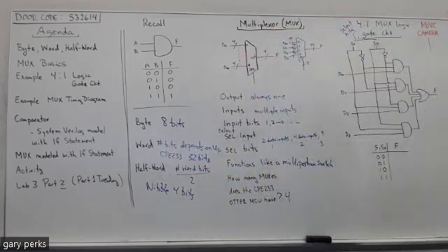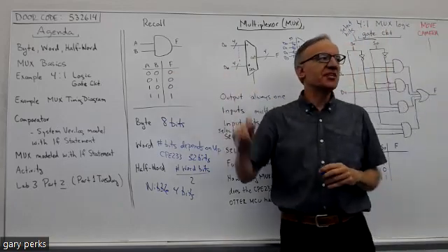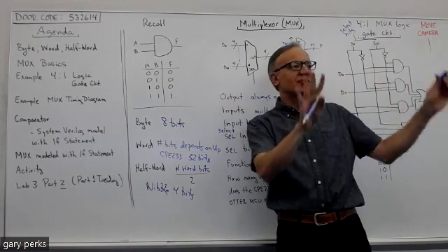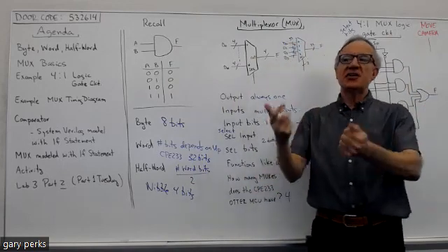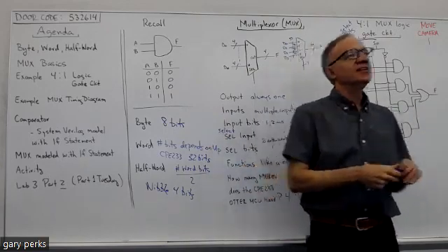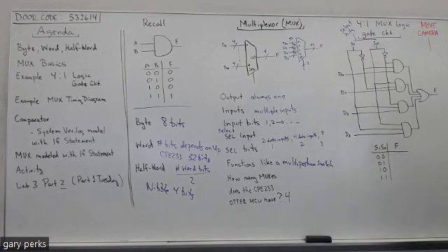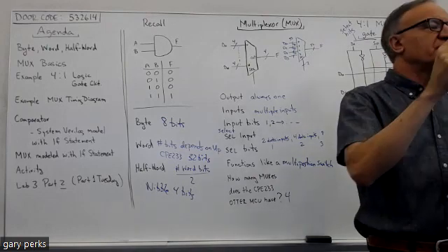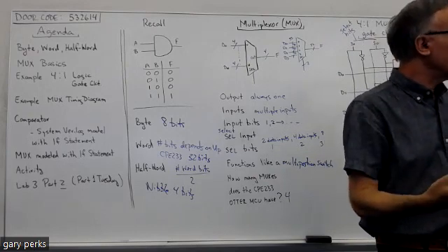Exactly, that you can get a NOT gate, you can get an AND gate, you can get an OR gate, and a NOR gate from a NAND, and same with the NOR, right? So we talked about that. And remember, when we were talking about those universal gates, we looked at the truth table in a certain way to see, oh, this is how I can use a NAND as an inverter, or, oh, this is how I can use a NOR as an inverter. And then we looked at De Morgan's for how to get a NOR to be a NAND and so on.